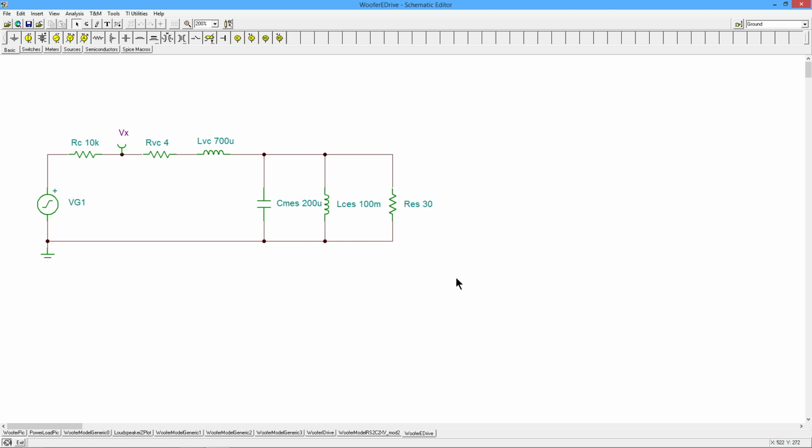Possibly you could use one of the applications. They have these digital scope applications for your computer using your sound hardware, your audio input-output. So theoretically you could do that, but I have to warn you, the output probably won't be big enough. You can get one of those virtual function generator apps. So you would have to use some kind of amplifier to crank that signal up so that you can drive the loudspeaker. You still need a pretty good sized signal out here, right? And that's not going to give you 10 volts peak, no way. So you'd have to come up with something to kind of modify that. But in any case, that is how you can do it.